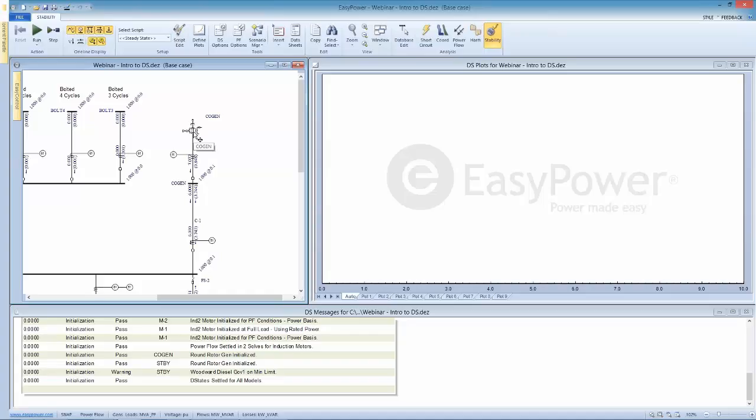The elements for the model include the rotating machine, which is indicated by this rotor symbol, the AVR or excitation system, which is denoted by the winding, and then the regulation or feedback for the power control is indicated by this little bow tie looking system over here for our amplifier.